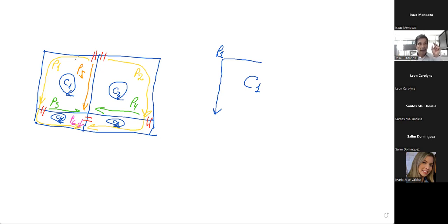You calculate the area and the distance to the neutral axis, and you can calculate large Q, the first moment. And you can do cuts along this path up to here, and you can calculate the distribution of the shear flow completely. But for cell 1, this is all we need up to here.